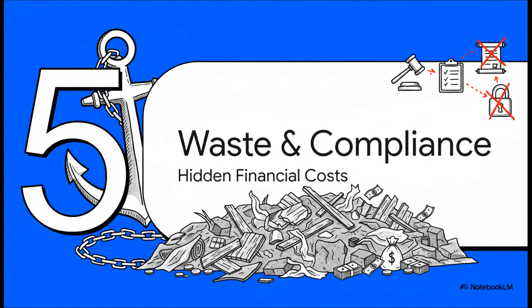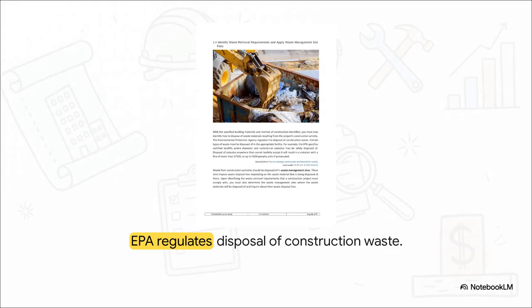Part 5, Waste and Compliance Costs. We are digging into the hidden financial anchors here. Which brings us to the final and honestly most frequently missed step of the initial dossier review. We have to account for the hidden financial anchors of compliance. You know, a lot of novices will calculate the cost of bringing materials onto the site, but they totally forget to calculate the cost of taking the waste off the site.